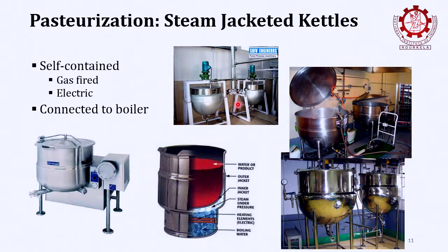There's a direct heating, which means you inject the steam in your product, correct? And the indirect heating is where you have the product in a container, actually you are heating the container, whatever way you are heating, right? Could be hot water, could be steam, could be a gas fire or electric fire. What would be the difference?